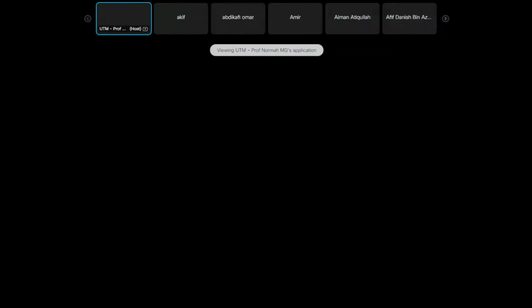For plain solid wall or plain fluid wall, the temperature profile is linear. There is no heat generation. Steady state, then the temperature profile is linear. Now, if you know the direction of heat from a higher T to a lower T, then you can just use this equation. This is for steady state, no heat generation. Heat transfer per unit length is given as watt per meter, or per unit volume, watt per meter cube.